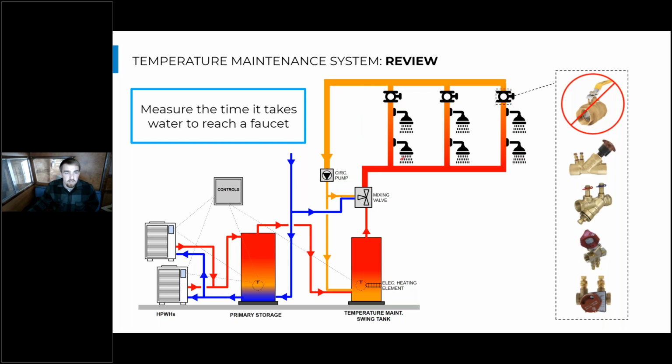We talked about how we're serving hot water, but we need to make sure that that hot water is always fresh and hot and hasn't had time to cool down before somebody opens a fixture and wants to access that hot water. If all of this water upstream of this last fixture here has cooled, that could be several gallons that takes a really long time to all flush out before new hot water replaces that.